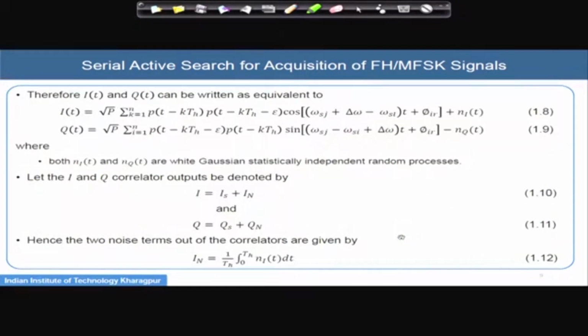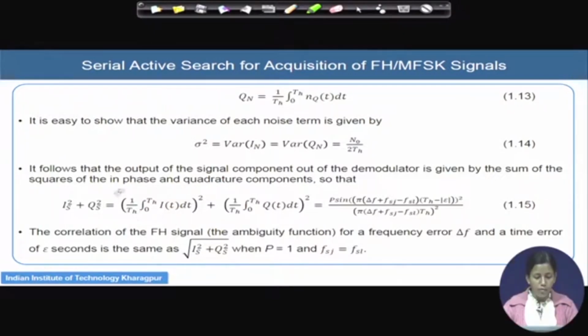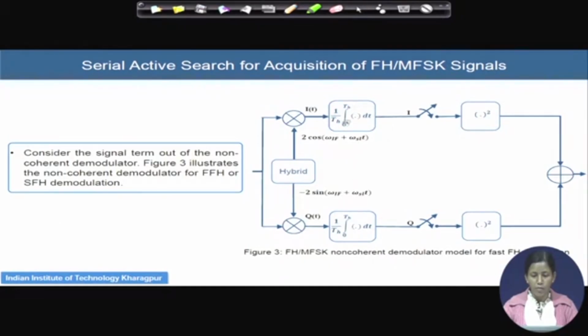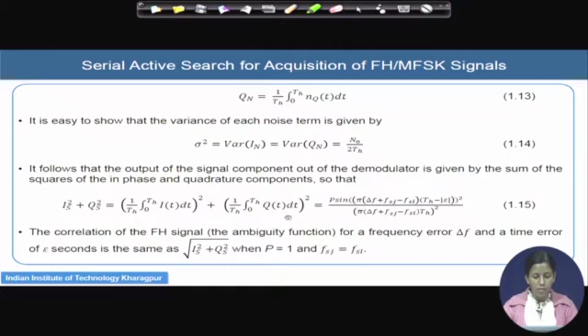So, for this adder output, we are looking at equation 1.15, and definitely it will be the individual integration and then squaring up. According to the architecture, it will be a first correlation, then the integration part, and then the sampled integration part is squared up for both the paths. The same thing we have done in the equation, nothing else.